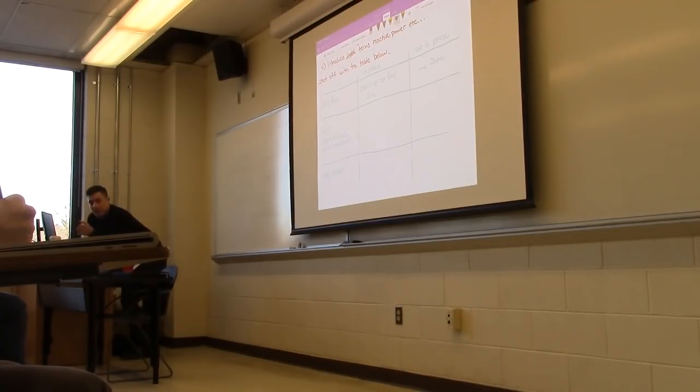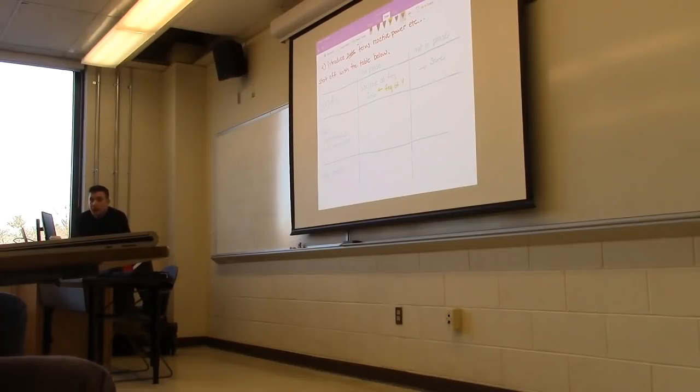So omega 0, or omega naught, is the frequency of the voltage as well as the current. For phasors, for the problems we're going to be looking at, the voltages and the currents will by default have the same frequency. Since we're doing this in phasor notation, they have to have the same frequency. So V naught, if we're talking about electricity from the wall, oscillates at 60 hertz, and therefore our instantaneous power is going to be oscillating at 120 hertz. Okay.